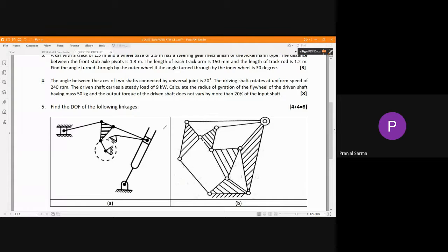So we have to identify the kinematic pair, sir. Yeah, first find out whether it is a kinematic pair or not. Okay, then the kinematic linkages are definitely given. After that, you need to properly number the different links and show them. Okay, you just need to draw this configuration diagram, and this is fixed link number one.